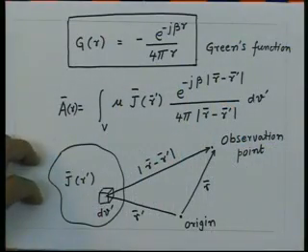We take the simpler cases and we assume that the current distribution is a priori given, and now we are interested in finding out what kind of fields will be generated by this current distribution. That is the problem of the antenna. So, in general, for simpler antennas, the current distribution is obtained in some other independent way, and then from the knowledge of the current distribution, we can go to this and find out the vector potential and then find the electric and magnetic fields.